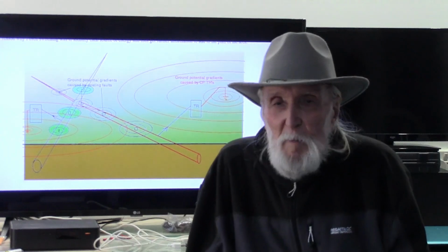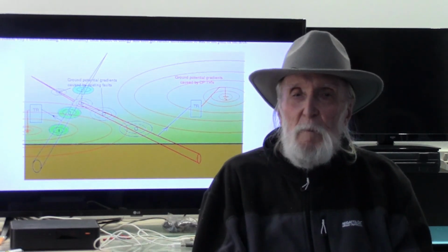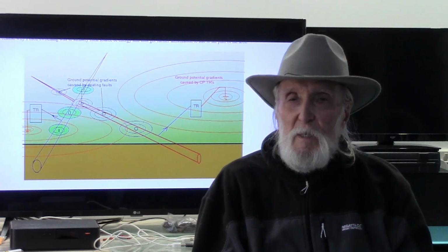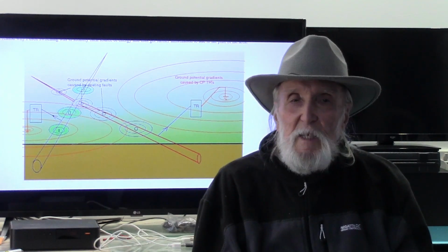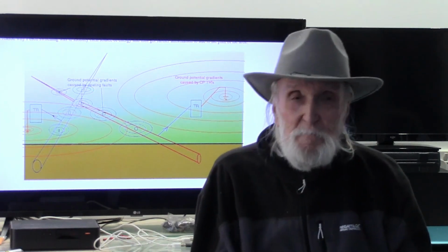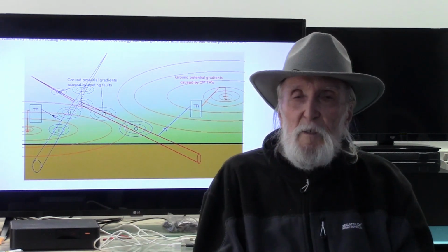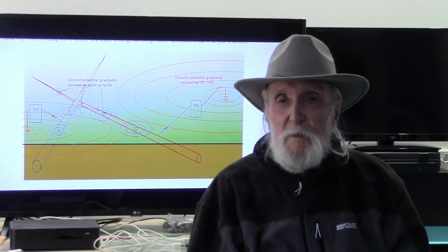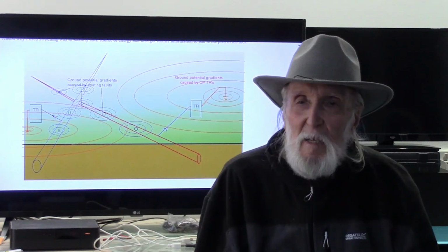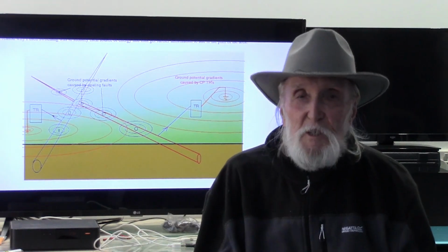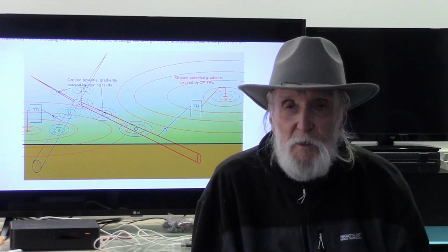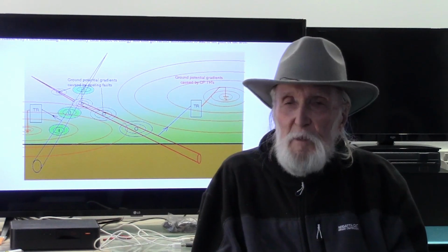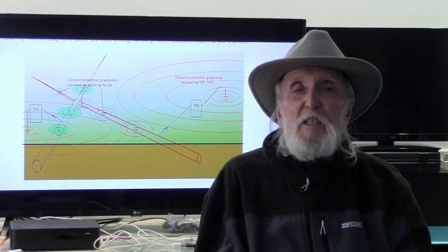If there is a steel pipeline in this path, then it will offer a low resistance path to the returning current. But if the coating is perfect, then it will not. In order to affect the corrosion status of the pipeline, there must be a point or points of entry to the pipeline metal and point or points of discharge from the metal into the ground. When the current enters the pipe metal, it will stop corrosion, but where it leaves, it will accelerate corrosion.